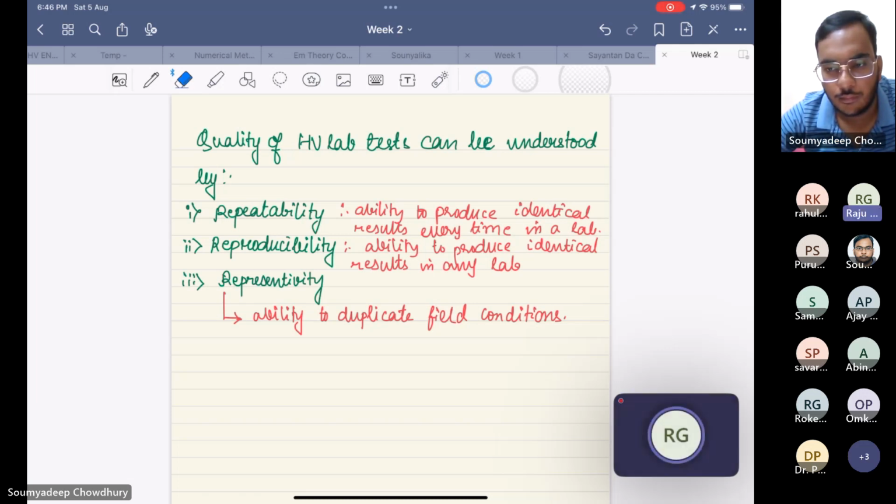But for the repeatability, the same voltage and other parameters may not be retained because the insulator would have deteriorated its property. Therefore, when you are doing the same test on the same insulator, I don't think the same characteristics will repeat. It will be different once it is tested. Exactly the same we don't want. Suppose today evening we get 15 kV, next morning we don't need exactly that. There will be a band of tolerance, obviously. So it will not be as significant as you are thinking.